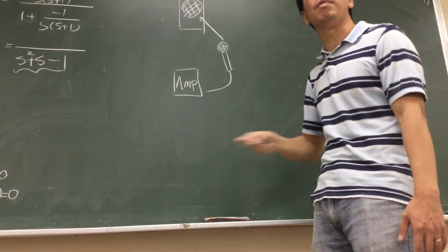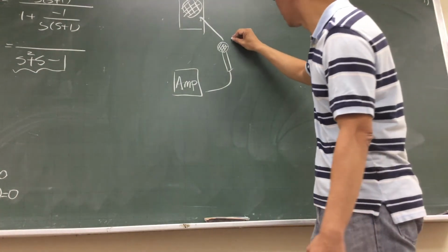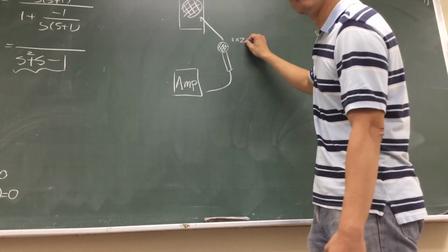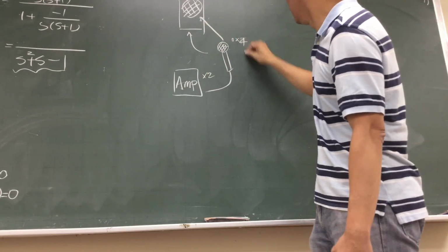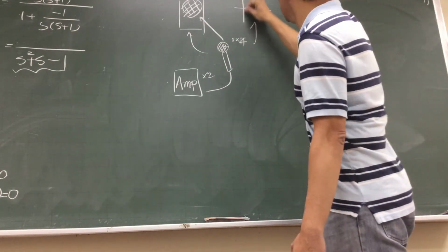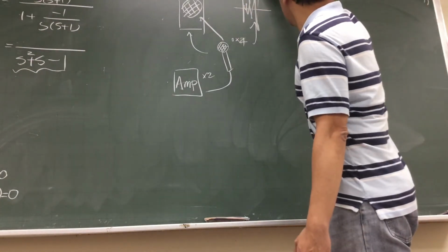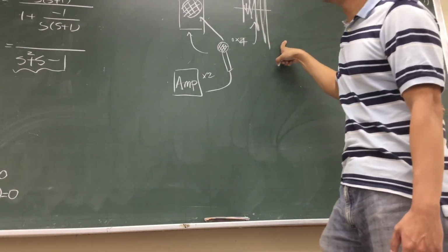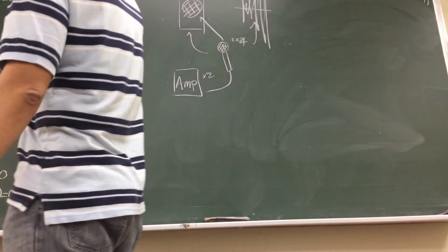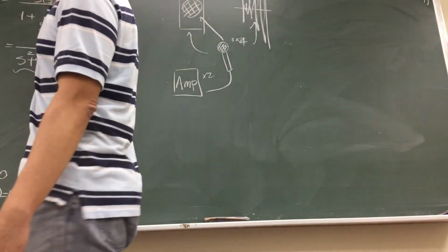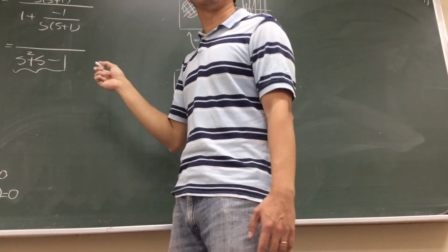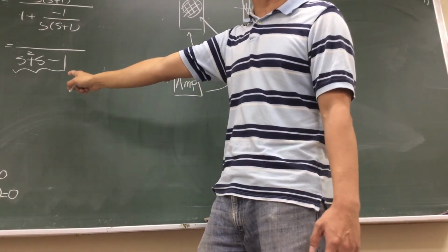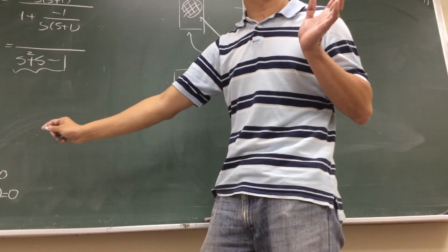That is positive feedback because you got a small thing over here, then you multiply by 2. Then go back to this one, it says multiply by 2 again, so you multiply by 4. And you keep on going, so it's going to be positive feedback. That is because you have a positive thing over here, negative thing over here, so everything goes back to the system, becomes positive feedback. So you're going to make your system unstable. Okay?